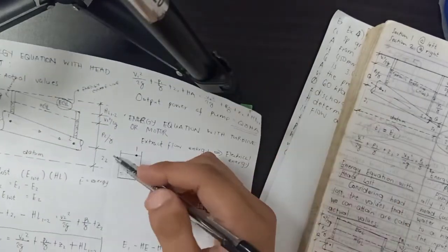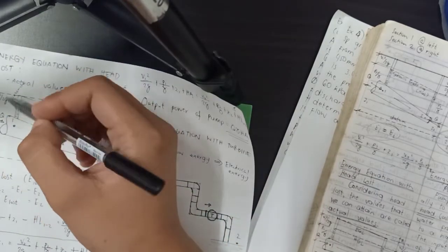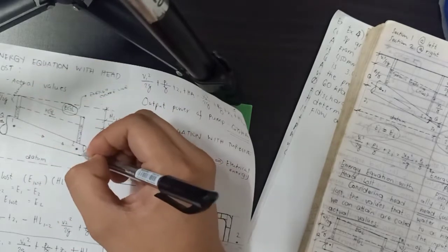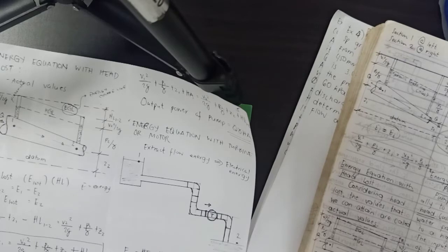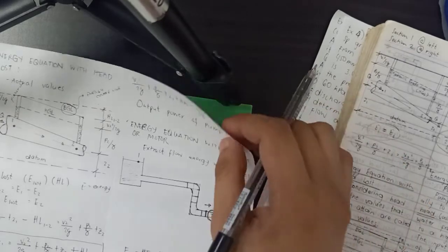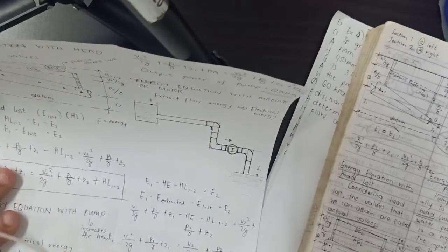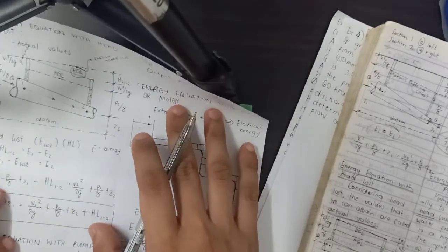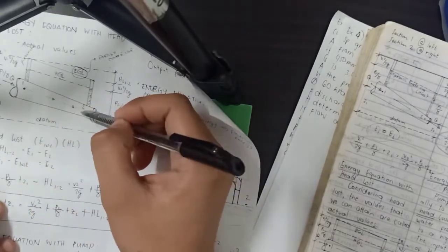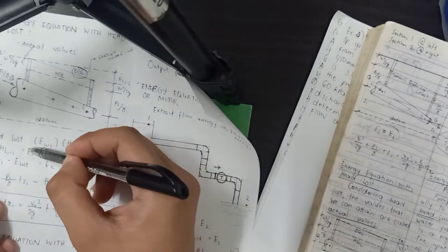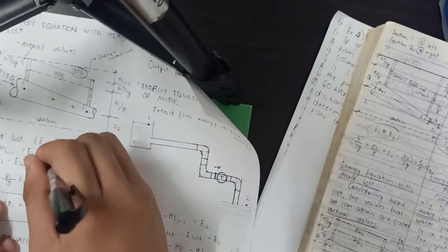Again and again, whatever, it is in the continuity equation. The flow rate at the end point is the same for both sections. They only differ in velocity. So, we will now form an equation. Head loss from section 1 to 2 equals the subtraction of head 1 and head 2.